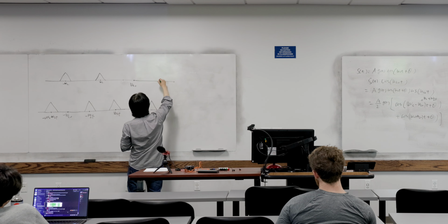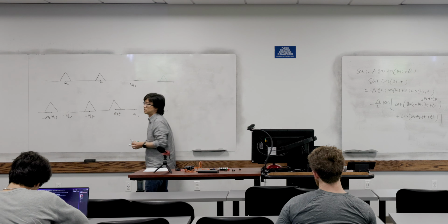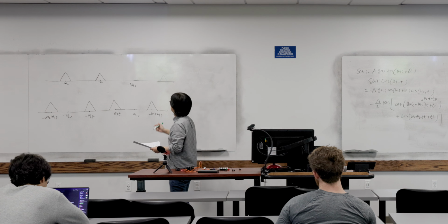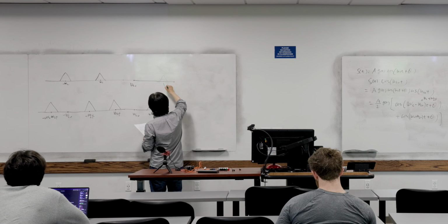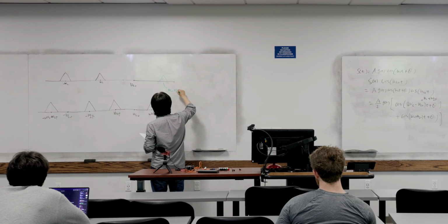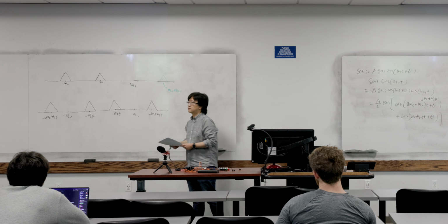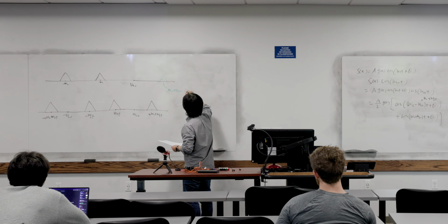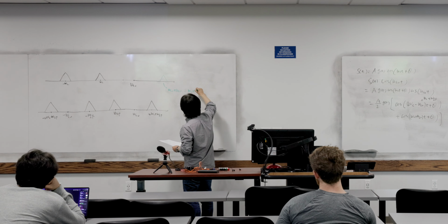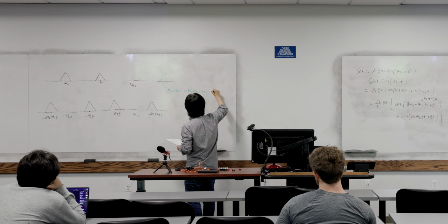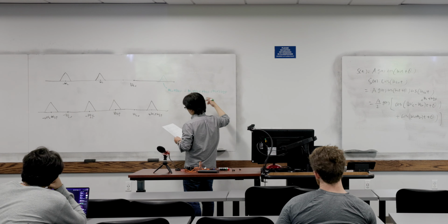Let's see, how about we have a signal here. And the frequency component in the middle, so that equals to what? WLO plus WIF, right? And that will be what? WLO is WC plus WIF, and plus WIF again. So that equals to WC plus 2 times omega IF.